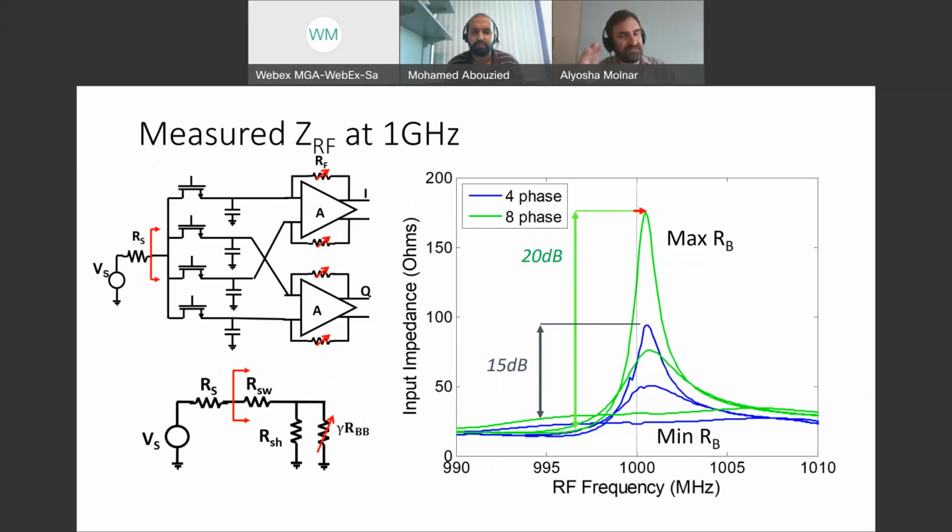So you actually get a slightly different interaction than you might expect, where the LC filter doesn't set your bandwidth, but does set your center frequency by guaranteeing that your mixer center frequency is centered up at the LO and not offset by the sort of interaction you see otherwise. So making the input impedance look real is maybe more important than the actual resonant bandwidth effects of an inductor. Okay.